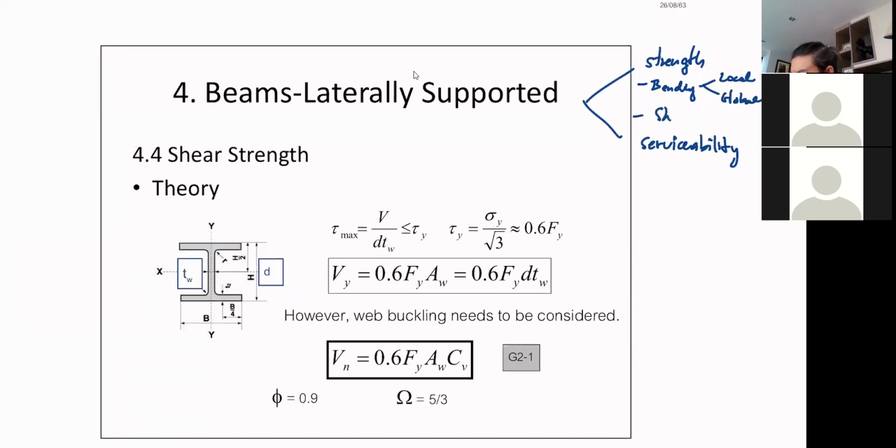And now you're going to have shear. That's our next important thing. Well, generally, when we are dealing with steel beams, it's pretty bending dominant, and shear is not going to be as dominant an issue as the bending moment. But still, as good engineers, you need to be aware of the fact that your beams can fail under shear, and therefore you need to check it.